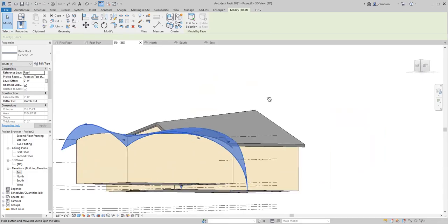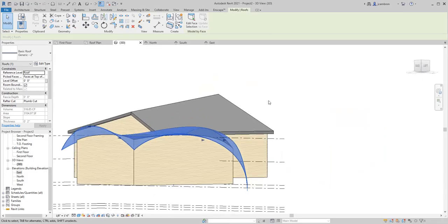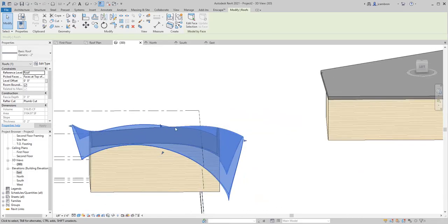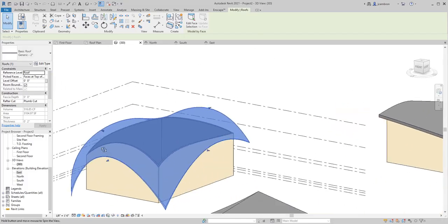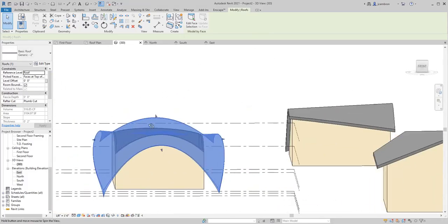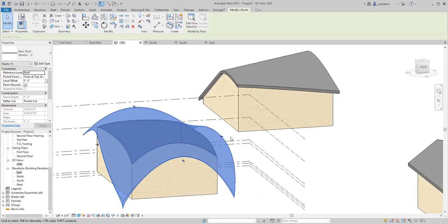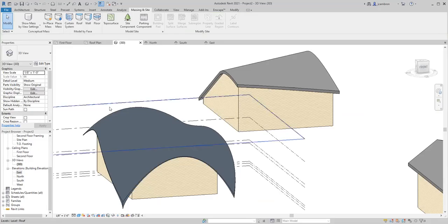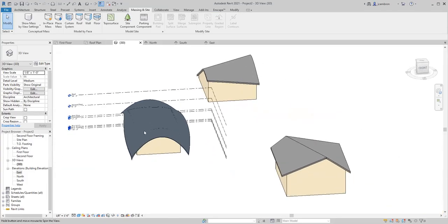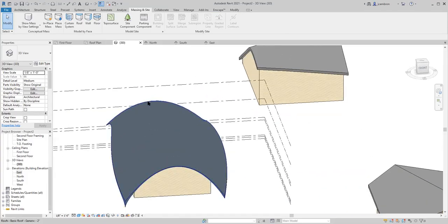Like I said, right before this lecture, I actually created the same looking structure. I must have overdone it somehow, maybe going on the outsides here, but I was able to create that same roof using a thicker roof structure, right? So it's just a matter of playing with it. Unfortunately, it's kind of a trial and error process that you're going to have to go through. But let's go ahead and stick with this 2-inch roof, and let's add some lights.